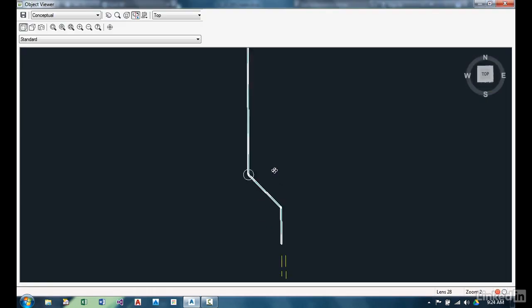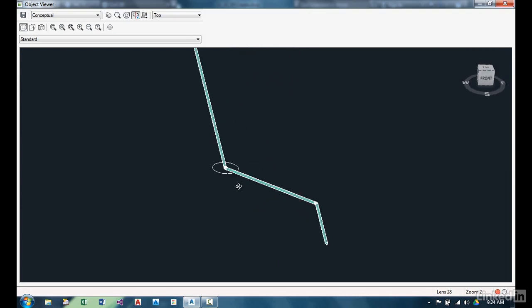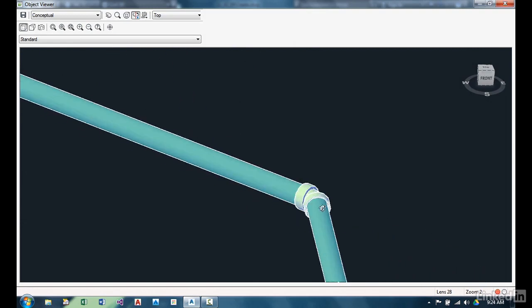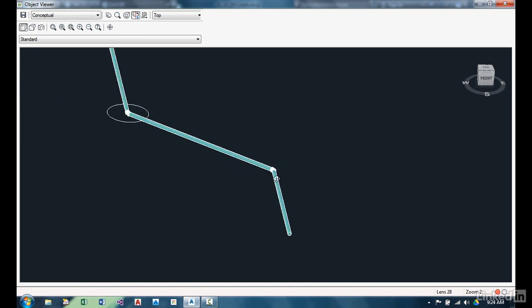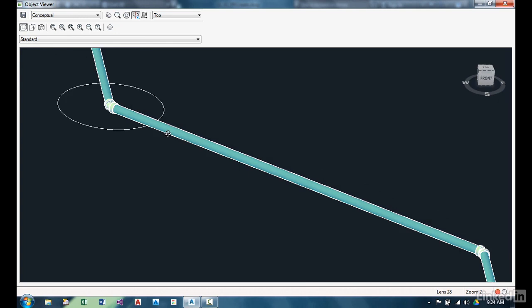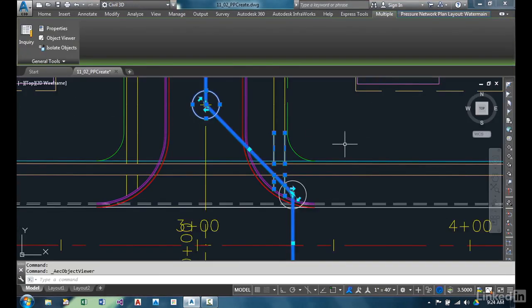And we're going to go ahead and take a look here, when we said they connected in 3D. And so this entire system now has been laid out. The pipe you see goes right into the fitting. The fittings and the pipes work together based upon the parameters or properties in the parts list to know, of course, the amount of deflection and what those fittings are capable of, how far the pipe goes in, and so forth. So there's a lot of information that is written back into the part itself, just as we saw with the standard pipe network system.